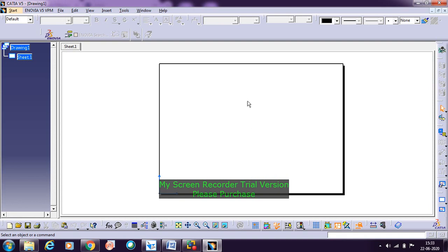In this sheet we need to convert the 3D drawing into a 2D drawing. So how to do that? Here you need to go with the view creation wizard. Click it here. We can get the front view, top view and left view here. In this case I wanted the top view, so with this I'll be getting the top view. When you go to the next option, you will be getting the front view, bottom view and then the right view. We don't want that.